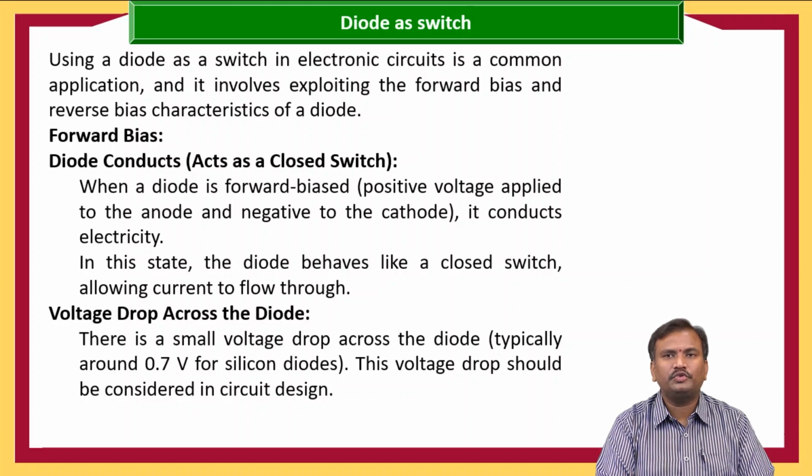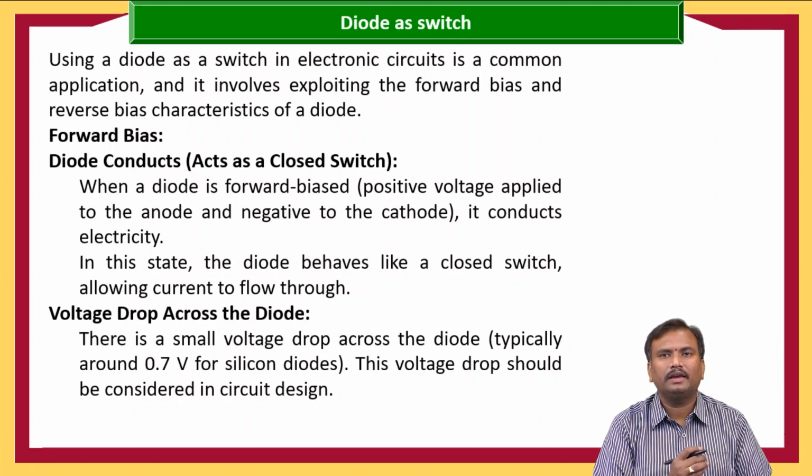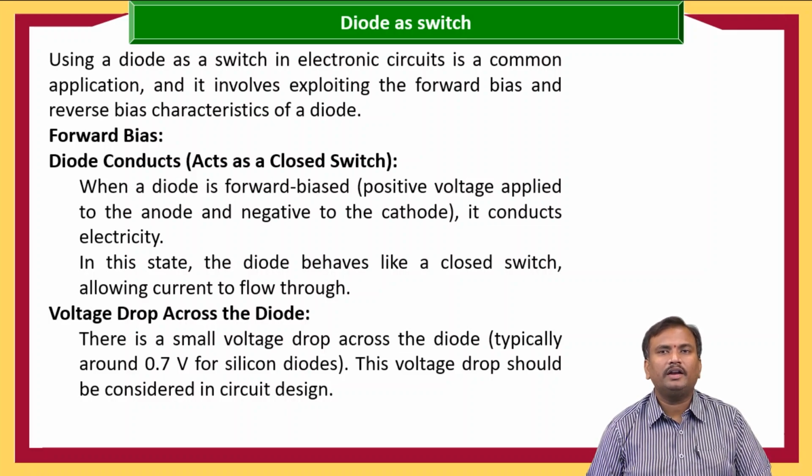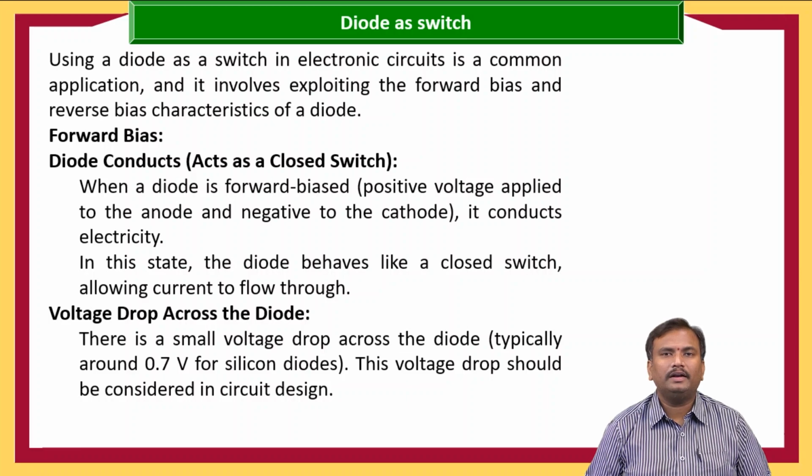This drop should be considered in the circuit design, because for every diode there will be some practical conduction voltage drop. That voltage drop we need to consider while designing the circuit.